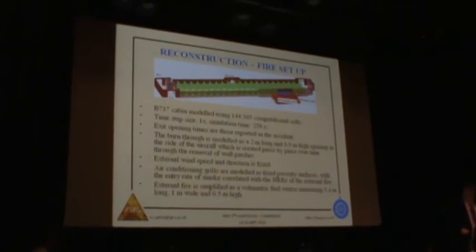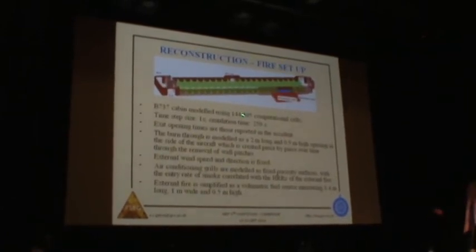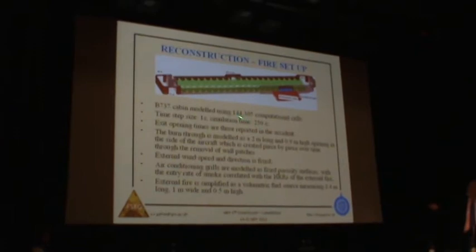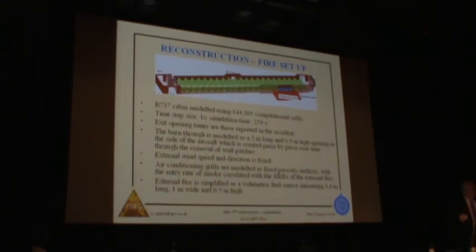The fire simulation, to give you some idea, that's the fuselage. We had 144,000 computational cells in this structure. We used a 1-second time step to march through the CFD calculations. Heat, smoke and toxic gases, CO, CO2, HCN and HCl, were predicted during the simulation. And we had a spreading fire model, so the fire was actually spreading and combusting the actual materials in the cabin.